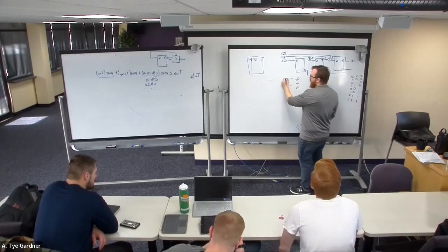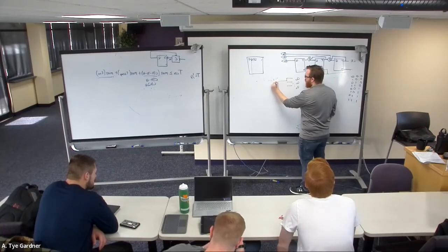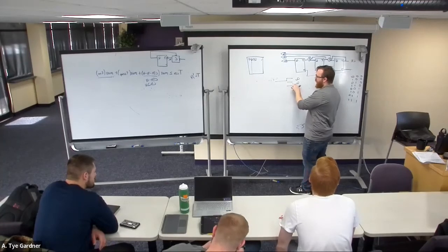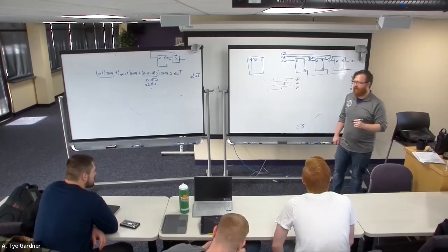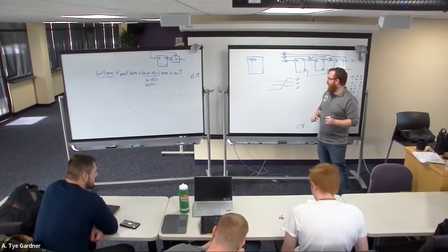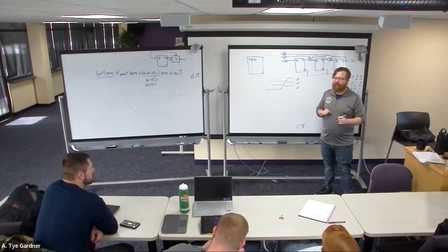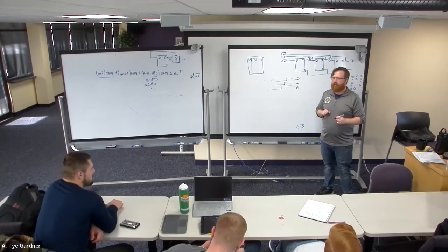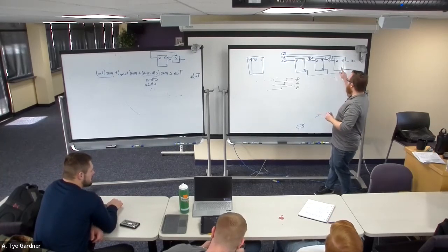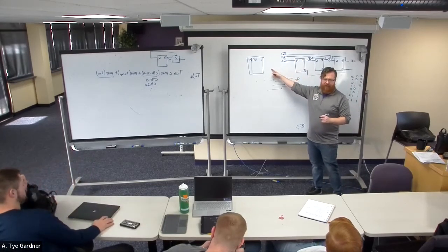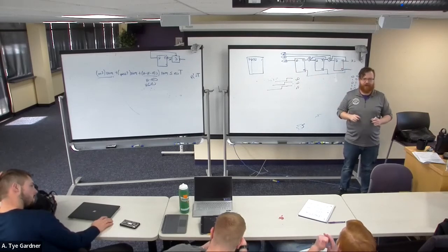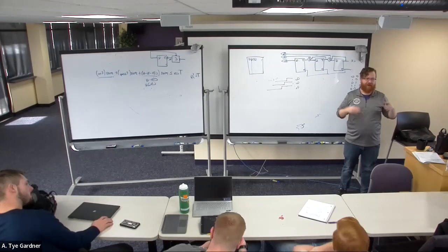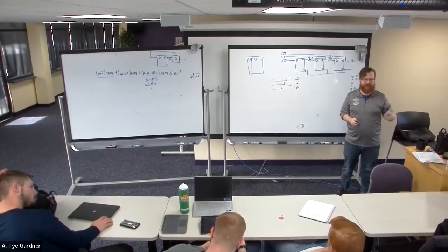So what happens is this one goes, oh, I'm supposed to be 0. And then this one, a little while later, says, oh, I'm supposed to be 0. And this one goes, oh, I'm supposed to be 0. So there's this cascade of delays that start to add up. If you count over it more than once, then that just gets worse and worse. So eventually the delay between the first bit updating and the last bit updating, the last bit won't update until the first bit has already changed to the next number. And you will not even for a moment have the correct number. And it's just going to be this weird oscillating nightmare.